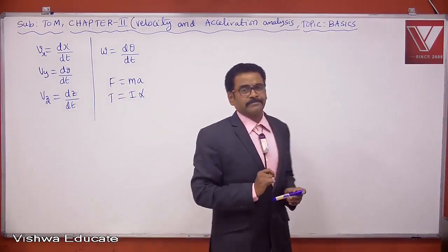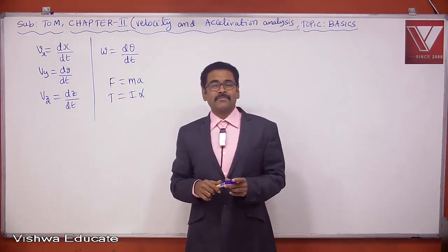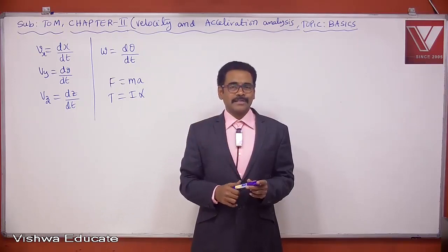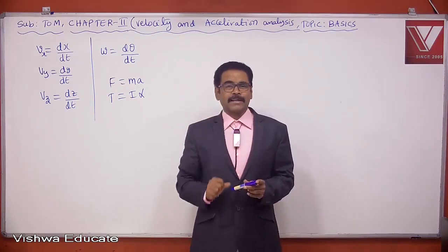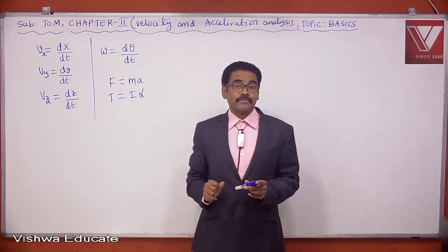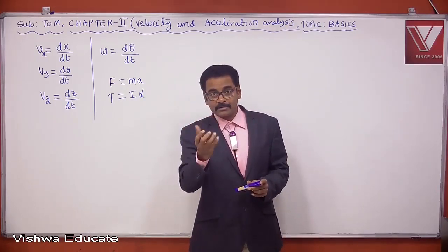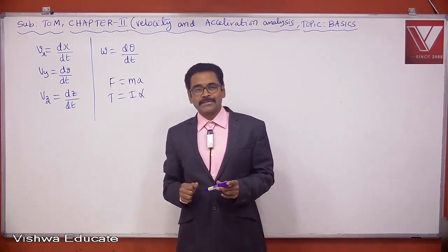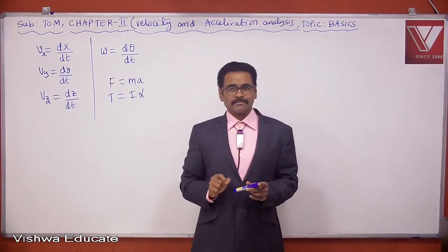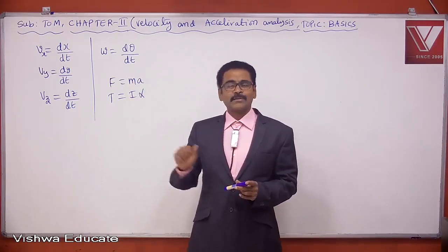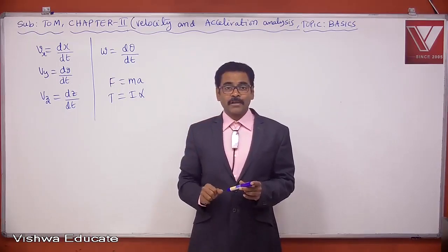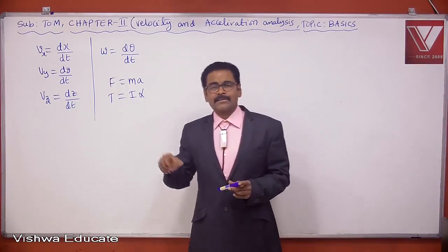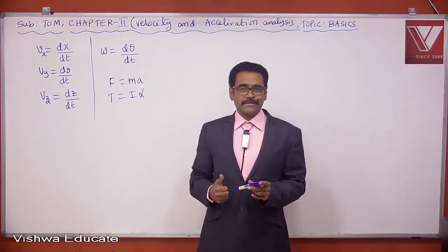Why do we need to find stresses carried by each link? I need to find stresses to fix the size of the link. More stress means more size I have to put. More stress means I need to use stronger materials. We have to perform stress analysis for designing of links. What is the size of the link? What is the cross section of the link? What material do I have to use? With what surface finish do I have to use it? All these things I can fix from stress analysis.